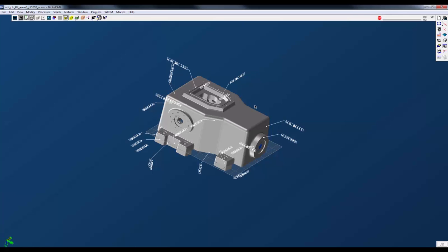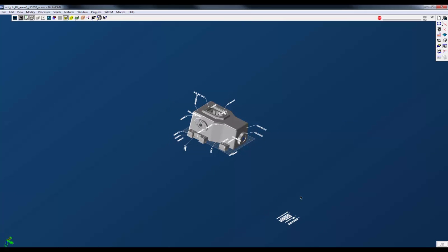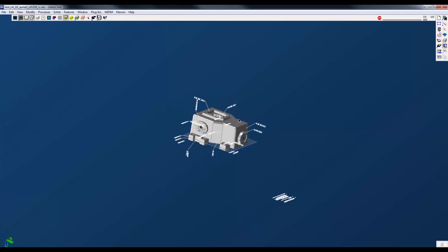You can turn on what you want to see, what's important to you for that manufacturing process, and maybe turn off what isn't important to you, maybe like this title block or something like that. So again, that's for step files, CATIA v5 files, and UG files. With the spatial translator, you can go ahead and open up files that have this product manufacturing information on there.